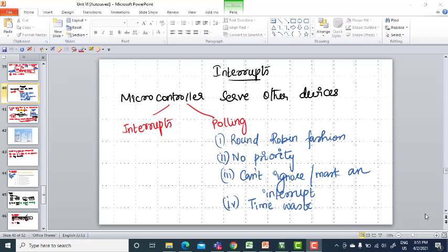And then when the count value rolls over from 00 to FF, the timer overflow flag will be raised to 1, indicating that the on time operation is over. Then what will you do? Complement the bit P1.0, and the next off time count will be loaded again in the timer register. Again you will enable the timer run flag to start the timer operation, and the timer operation will continue on and on. Am I right? Continue on and on.